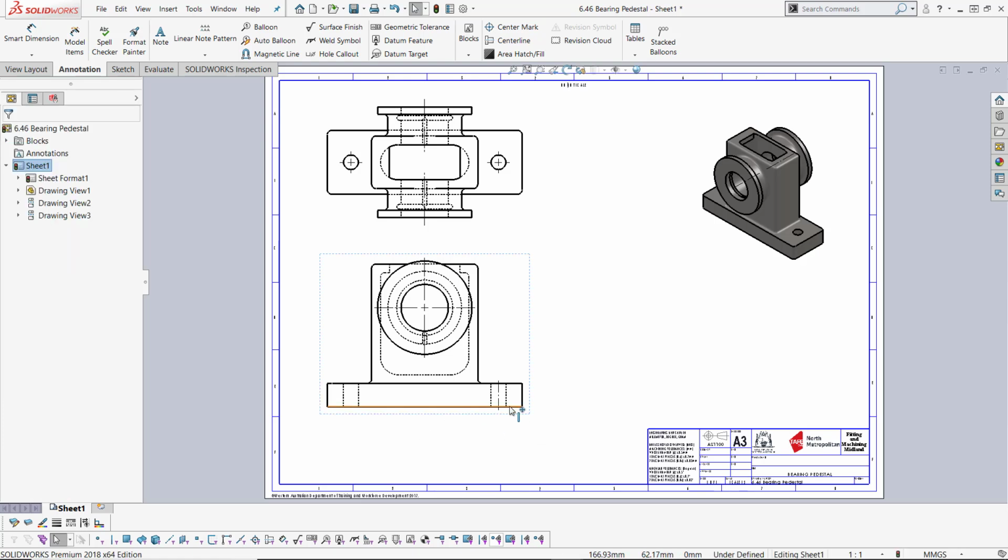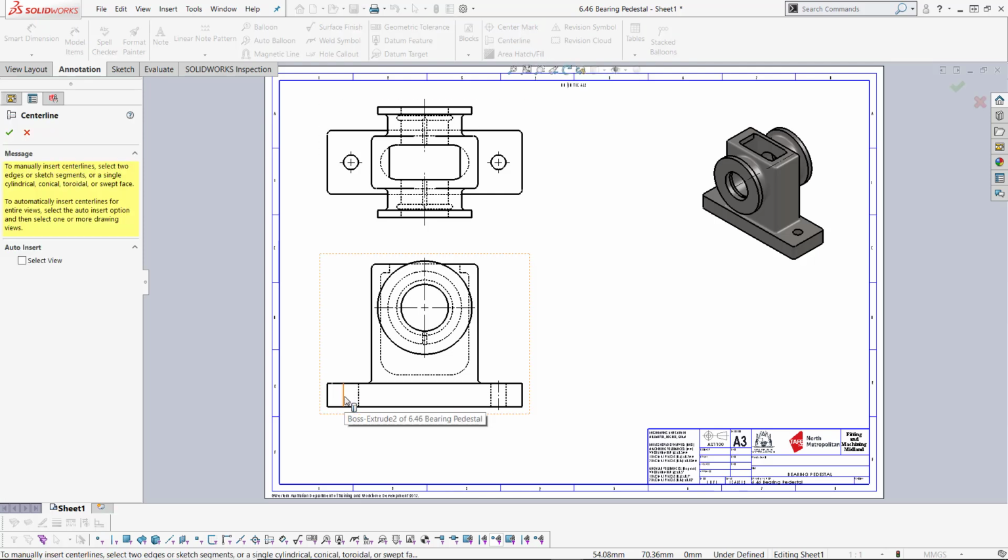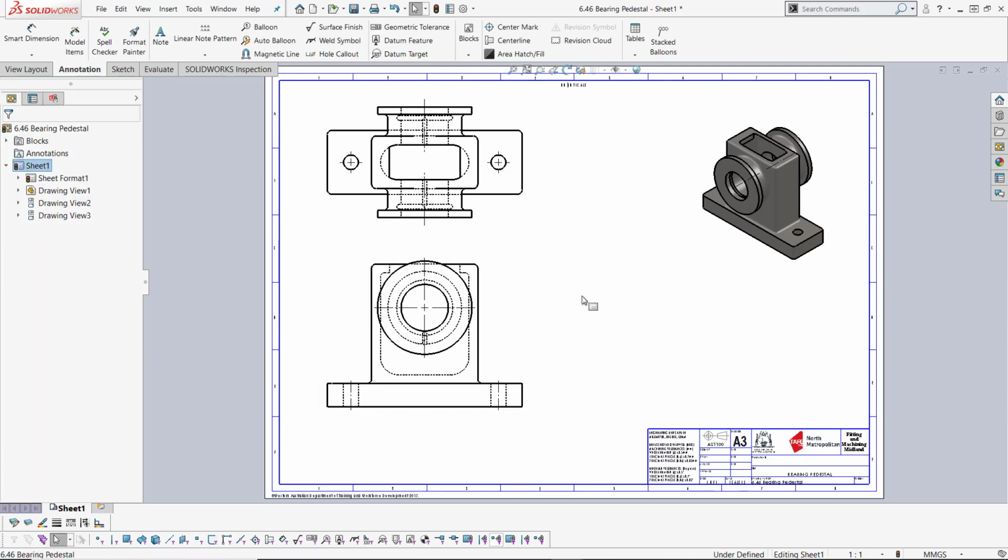Okay, now because it didn't insert the center line on this left hand hole for some reason, I'm going to manually insert that. So center line, and I'm just going to click those two hidden detail lines and click OK to that. That pretty much gets me predominantly all the lines I want. Now I definitely don't want these center lines in my isometric, and that pretty much has got where I want to start off with, my two main views and an isometric view there.